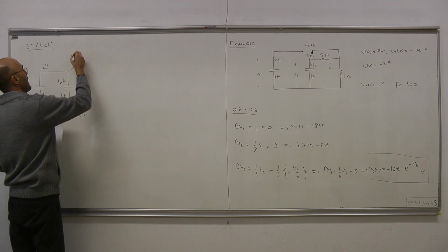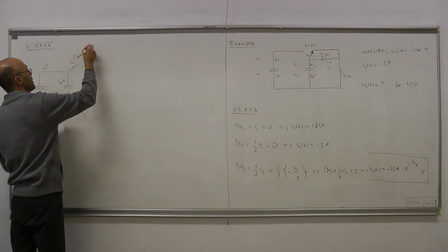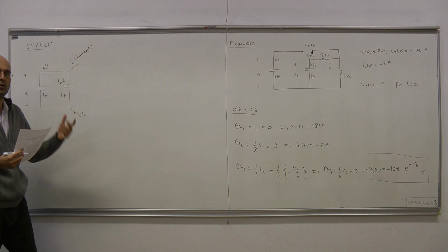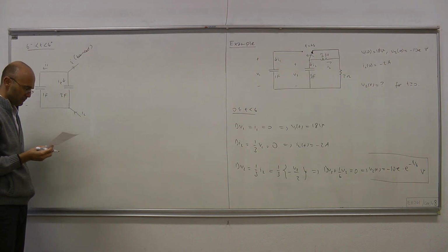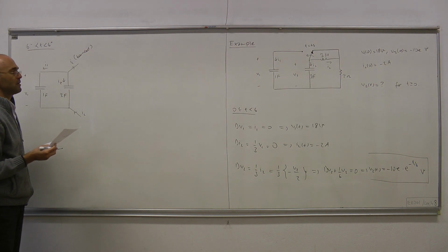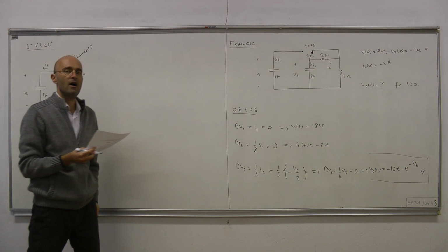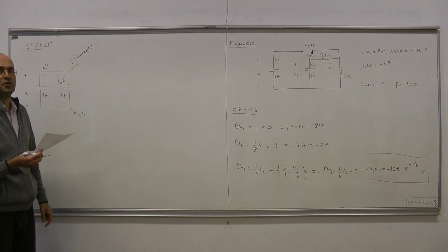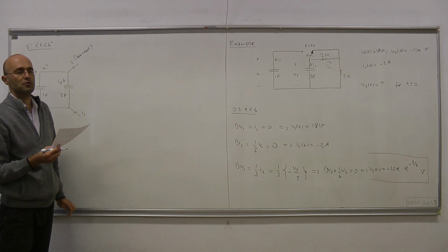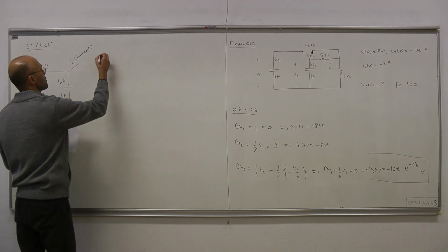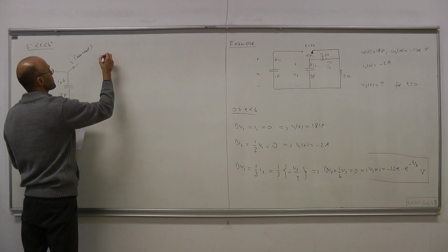Now what we know about IL, and we will use that information, is that it's bounded. Because by our assumption, inductor currents and capacitor voltages are bounded. And using that information, now we will be able to figure out how the capacitor voltages readjust themselves when the switch changes position. Okay, so for that, let's write the terminal equations.